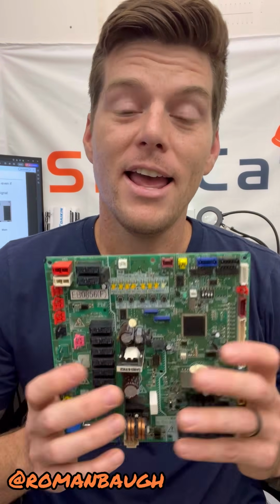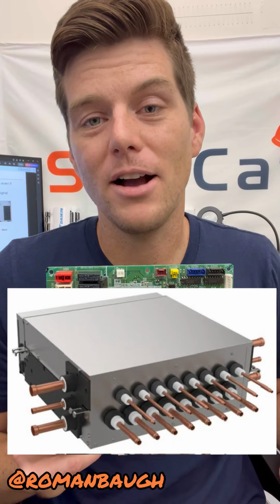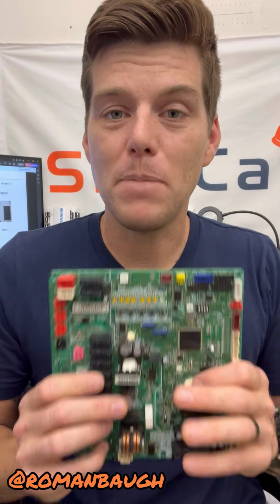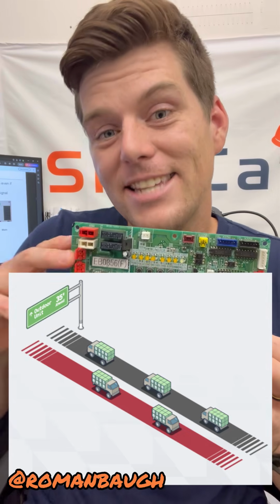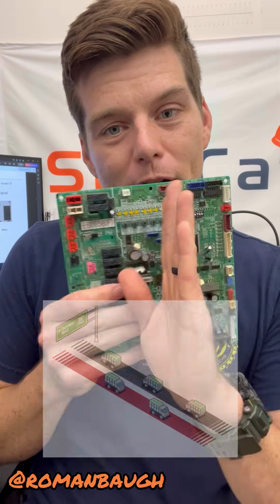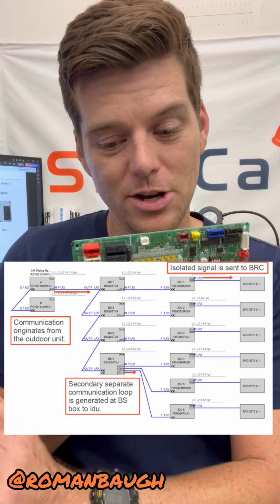Well, when we add a heat recovery system, it's now this talking to a branch selector box or a BS box, and then that box turning around, taking those information packets that it got, and then sending them to the indoor units. And so there's that break in communication between the outdoor unit and the BS box, and the BS box to the indoor unit.